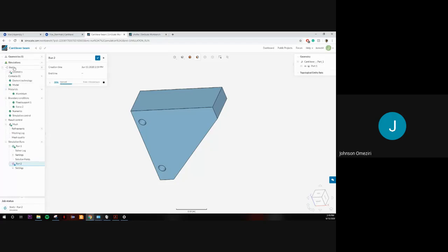So usually to fill this out, you just literally go down the tree and put in each piece of information one at a time. The only part that might be a bit confusing is the support. Just remember that this is fixed support and you're applying a force on the top. Then the mesh, just use the automatic mesh. You don't have to change any of the settings there.